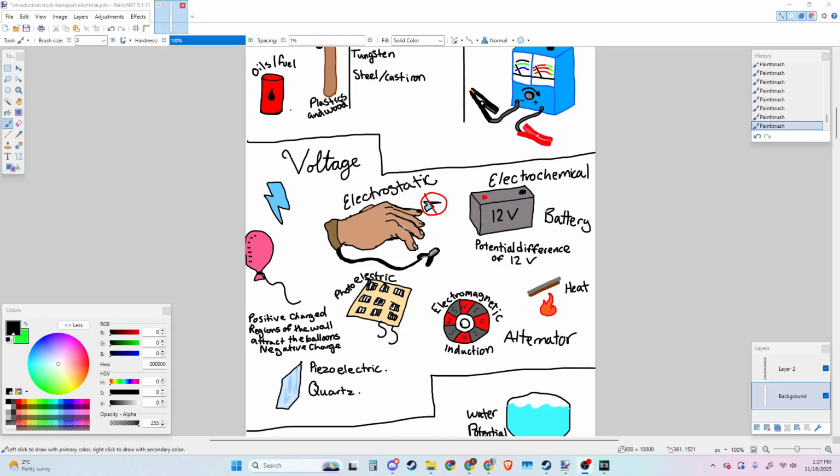But just know that static electricity can cause a lot of damage. Electrostatic shocks that produce light are thousands of volts. If you think about your standard car battery, it's 12 volts. How come an electric shock doesn't do a lot of damage? That's because the amount of current flowing through that electric shock is minimal, but it's at a very high voltage. Although it doesn't affect the human body, it sure can affect electrical components.